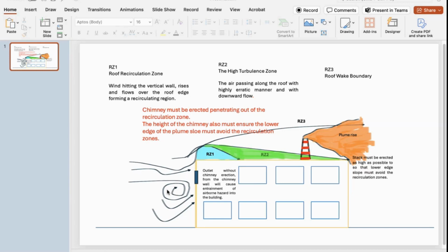So a person who has the system must be able to control every component. That means you have to ensure that you have an adequate amount of capture velocity, an adequate amount of transport velocity, good filtration velocity, no erratic drop in static pressure, differential pressures between components, between elbows, between filters, well taken care of, and efflux velocity, which can become a very good performance index in managing this. Why?